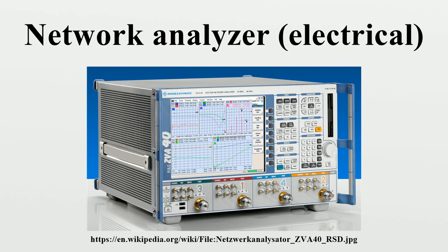The operator connects one box to the network analyzer. The box has a set of standards inside and switches that have already been characterized. The network analyzer can read the characterization and control the configuration using a digital bus such as USB. Network analyzer verification kits. A number of verification kits are available to verify the network analyzer is performing to specification. These typically consist of transmission lines with an air dielectric and attenuators.